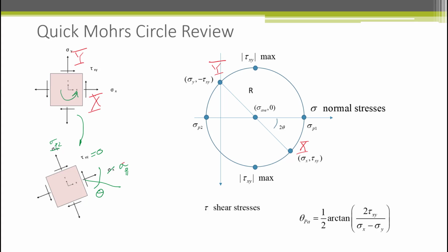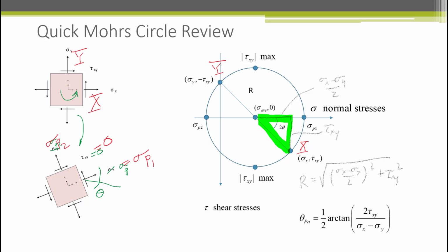The first step in developing the Mohr circle is to plot sigma x and tau xy for the x and y face normal stresses. After that, the radius of the Mohr circle can be determined, and the radius is the magnitude of the shearing stress. While the angle of rotation can easily be computed as shown in our earlier models, we are interested in the absolute maximum shearing stress to make sure that we are not approaching a shearing stress failure.